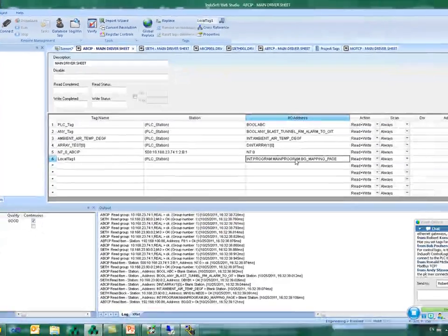The main thing about that is that you will need to buy the OPC server for Rockwell, while the ABCIP driver is part of the product. As you buy the license for InduSoft Web Studio, you get all the drivers with that. Okay, only a couple of specific drivers you pay separately, but you get more than 200 drivers with the license itself. And the Allen Bradley ControlLogix is part of the license. You don't need to buy any extra. Okay, so it's part of the product. That would be the only difference, Bob, with using RSLinx as OPC server.